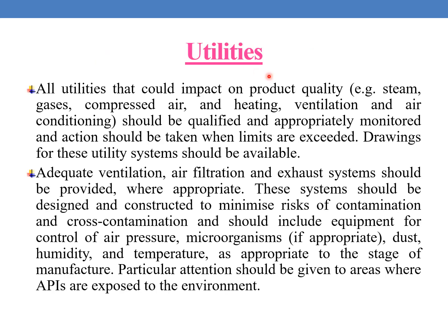Coming to utilities. All utilities that could impact product quality, for example steam, gas, compressed air, heating, ventilation and air conditioning, should be qualified and appropriately monitored, and action should be taken where limits are exceeded. Drawings for those utility systems should be available. Adequate ventilation, air filtration and exhaust systems should be provided where appropriate.